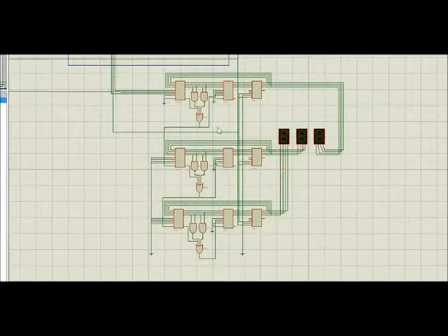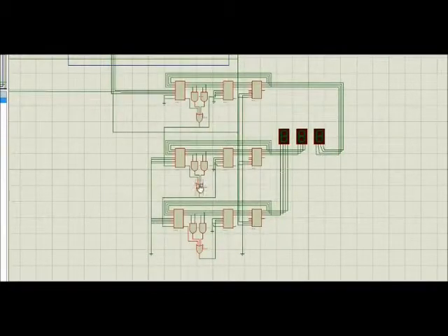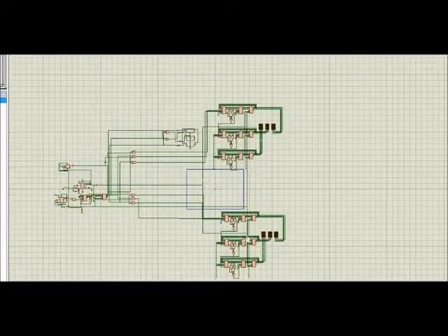The adder circuit of our game is capable of adding up to decimal 999, and to do this we required 6 7483 4-bit binary adders, 3 74195 parallel access shift registers, 6 AND gates, and 3 OR gates. In our game we needed 2 of such adder-cum-BCD converter circuits for the 2 players.